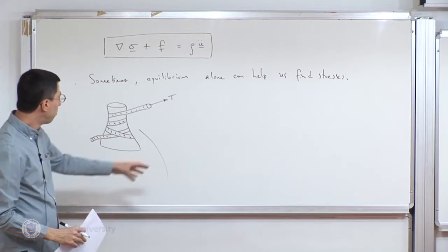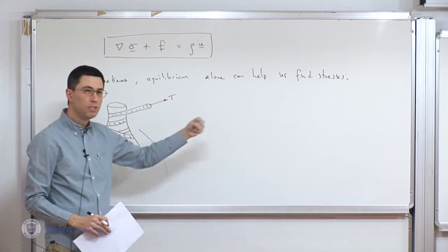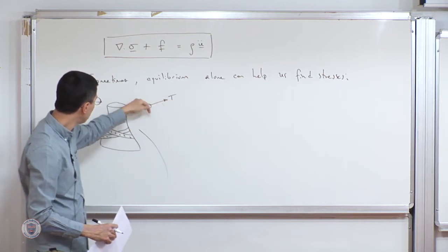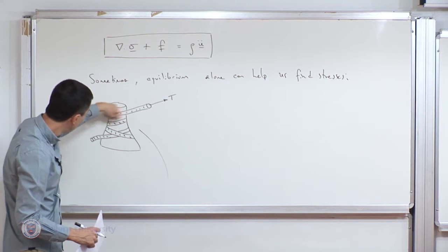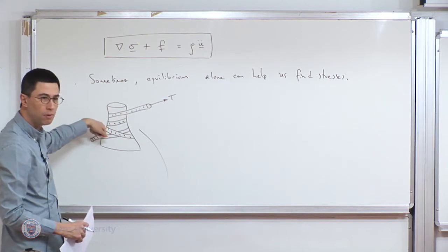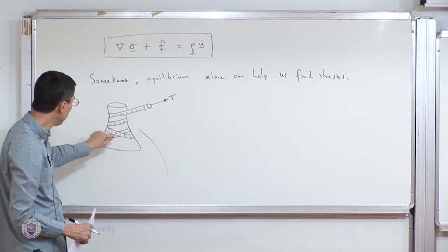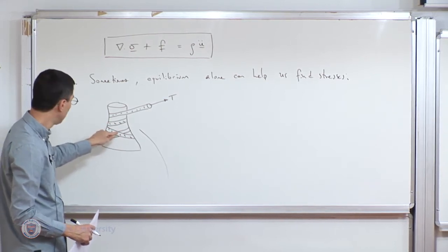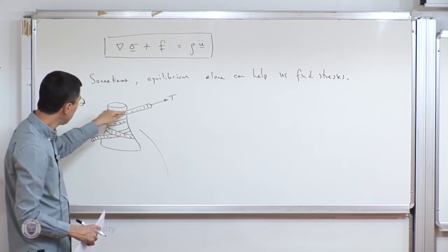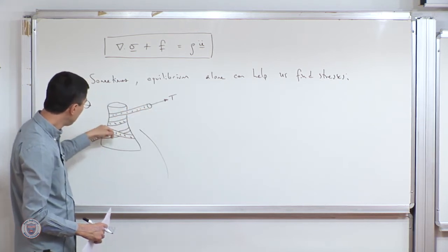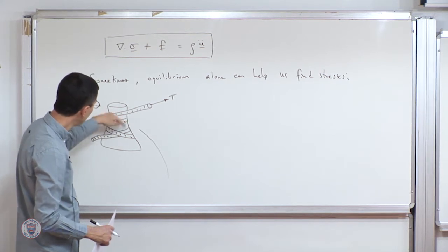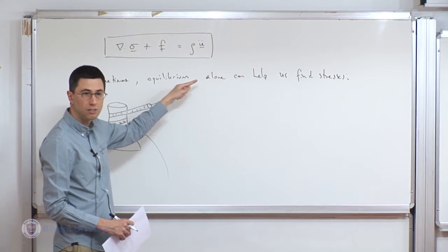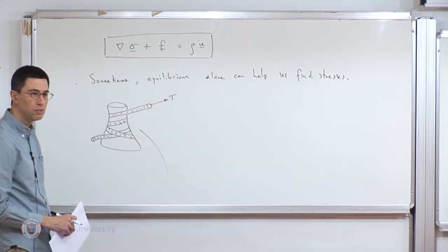And you know that boats are eventually heavy things. They can exert really high forces. That force is there because this rope is holding this thing. But what people do is wind this rope around the steel post a few times and make a small knot. The purpose of this small knot is to initiate some small tension in that region. And eventually, it turns out that although you can easily put this knot here, just after a few turns, this rope can carry a very, very high tension. Okay, so we're going to analyze this simple problem.